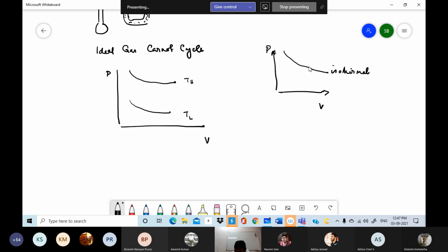To keep the expansion isothermal, I have to supply that Q. If I do not supply that Q, I expect that the temperature will drop. The internal energy provides energy for the work done, so the internal energy drops and consequently the temperature drops.